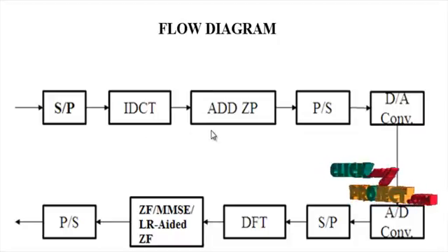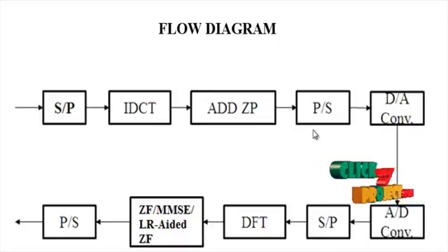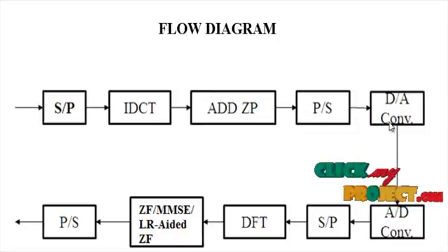The intrinsic design of an OFDM system prevents interference among the carriers, also called subcarriers. Inserting a cyclic prefix before transmission can avoid intersymbol interference. OFDM also has the ability to select channel selectivity both in frequency and time.